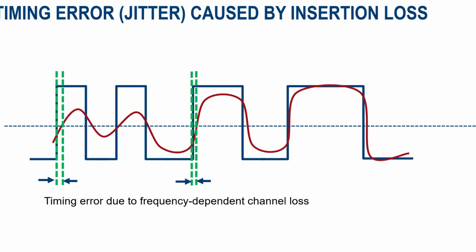And this is not the best diagram in the world of drawing, but it gives you an idea of what happens as the signal attenuation is higher in the 1-0 pattern sections. You're going to see a lower amplitude and a lower rise time as well. So effectively the crossing point at that threshold is going to shift, as a result of that attenuation and even potentially reflections. So what we want to measure is essentially that effect on our digital signal.